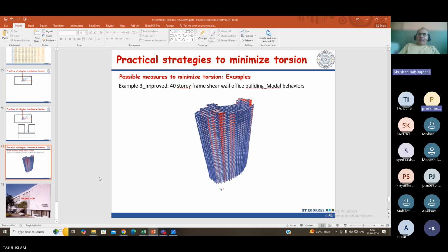Okay, so we'll verify the column. Because nobody knows whether the torsion should be taken or not in the walls, that's why I'm checking. So that also needs to be verified. Torsion is converted into shear, basically. Torsions are converted to shear in 2D elements. That way only it works mostly. Yeah, that justification needs to be checked.